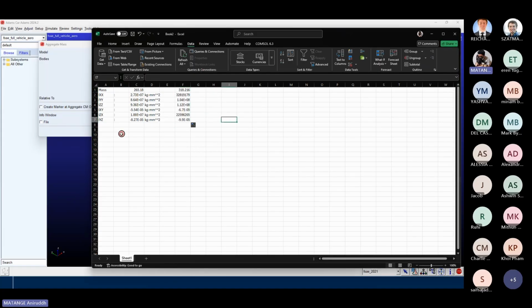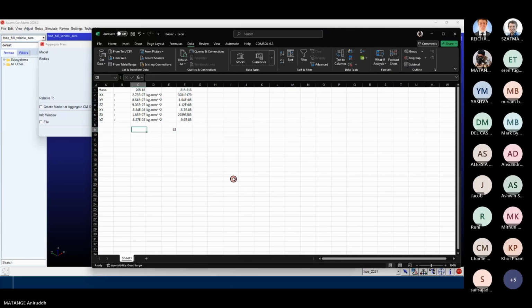And the other thing that we know about the vehicle is that you have a 45:55 ratio, which means that 45% of the mass is in the front, which means it's this amount of force on the front axle. Assuming that your car is perfectly symmetric, your front left and front right tires should roughly have this amount of normal force that they're supporting.